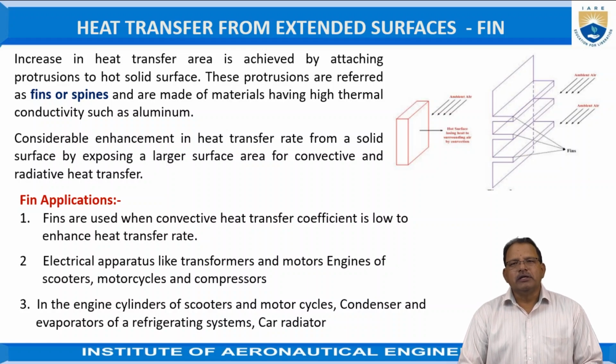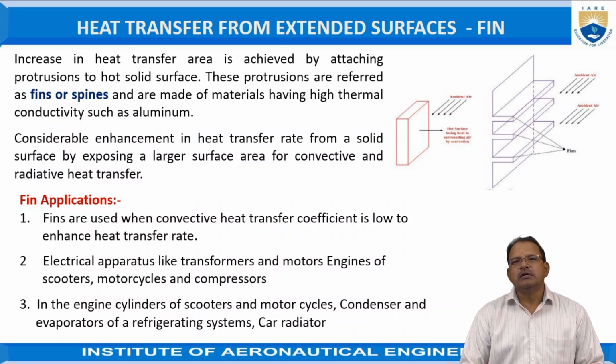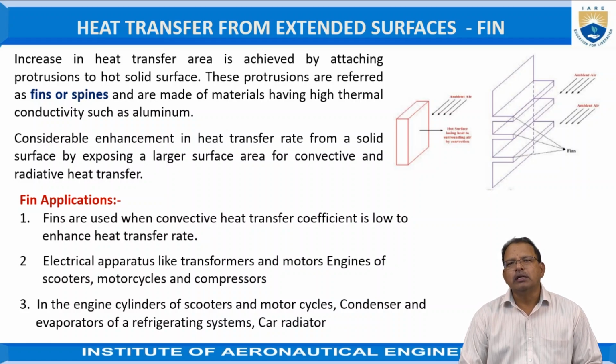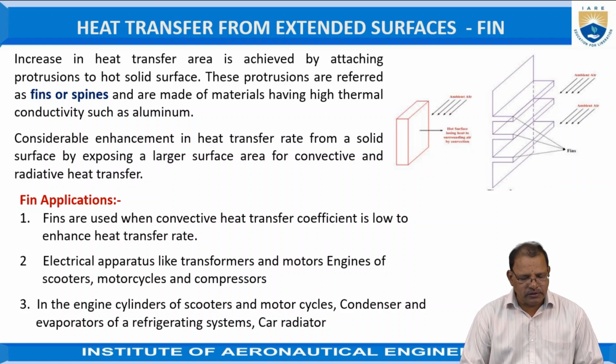Fins are generally used to transfer heat from a source, which may be electrical appliances or the automotive sector, to the surrounding air. Fins are used when the convective heat transfer coefficient is low, to enhance the heat transfer rate.